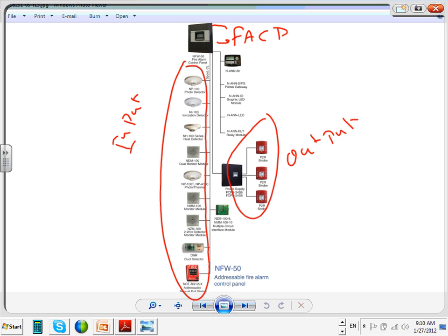Look how we're jumping from raceway to fire alarm system. Interesting. But I promise you guys will have good speakers and good information about this. For the time being, I want you to know that the smoke detector, heat detector, all these detectors, the pull station, you bring them to the fire alarm control panel. Out of the control panel, decisions are made and sent, for the most part, to a horn strobe like that one you're looking at. So it warns the people of the existence of a fire. I'm going to stop at that, at least at this point.